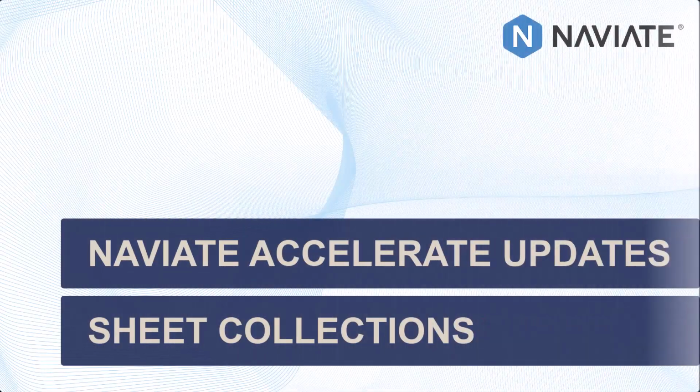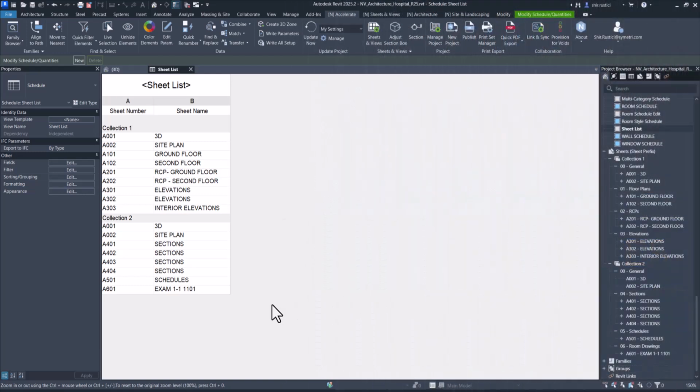We have also included improvements to our features that reflect improvements in Revit 2025. One of those improvements that was released in Revit 2025 was the ability to create sheet collections. This allows you to have the same sheet numbers in your project as long as they are in two different sheet collections.